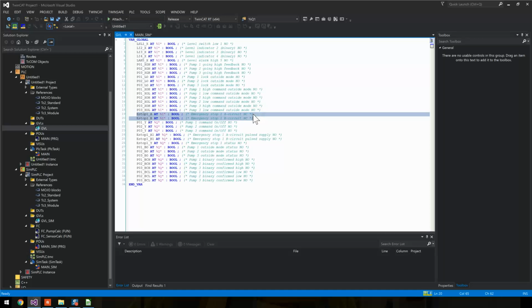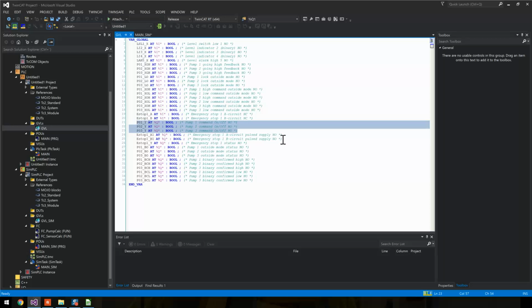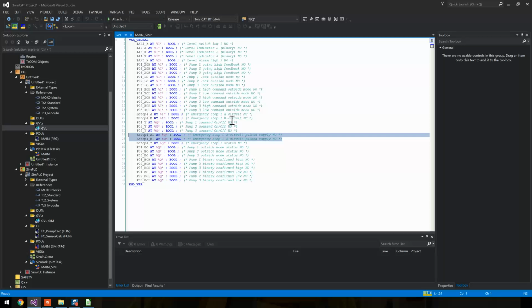This is the emergency stop button. This should always be high, otherwise something's wrong. We can also just simulate that one like these. These we have simulated. This is output to the emergency stop. So the way this one works is that we'll set 24 volts on one of our output cards, or two of them.